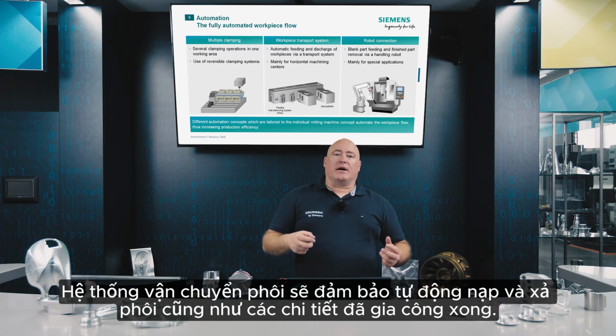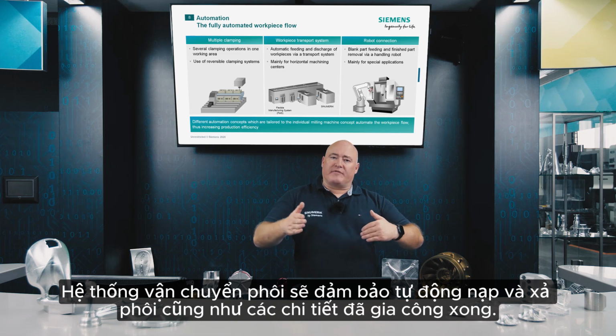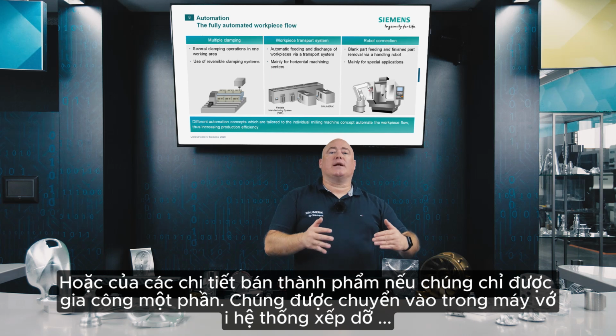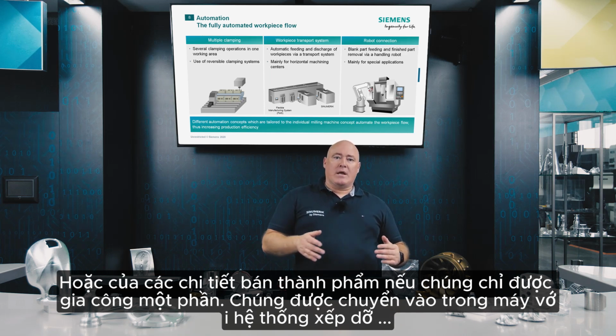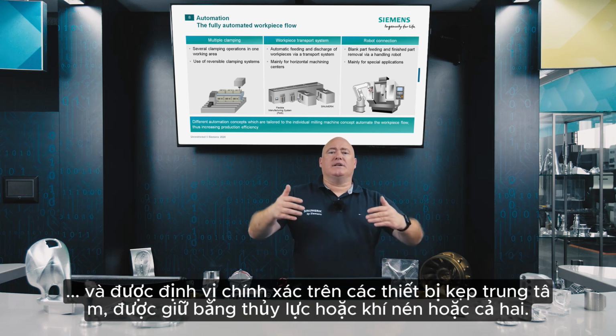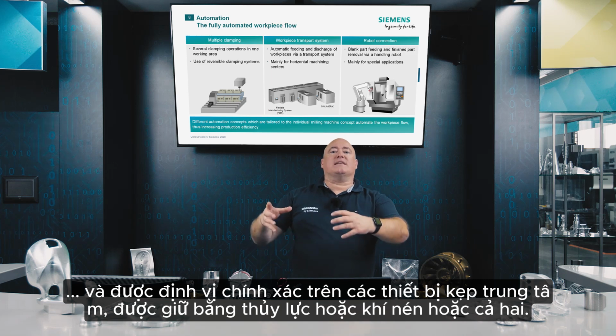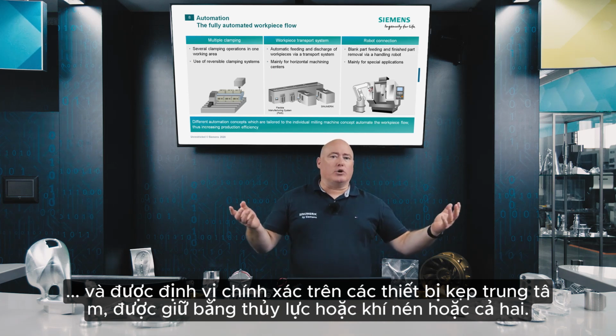Workpiece conveying systems ensure automatic feed-in and feed-out of blanks and finished parts, or also of semi-finished parts if they're only partly machined. These are moved into the machine area with palletizing systems and positioned precisely on central clamping devices, which are closed either hydraulically or pneumatically, or both.